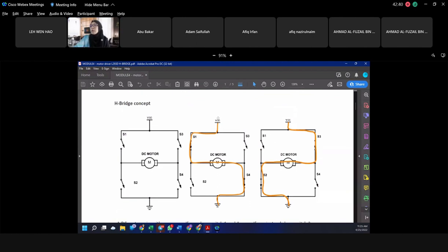So VCC here is actually the enable pin. You can see that the enable pin is always 5 volt, so we didn't change the VCC here. Therefore, we are not controlling the speed of the motor. Instead, we're just controlling switches 1 and switches 2, meaning the pair: whether you want to turn on this one or this one.